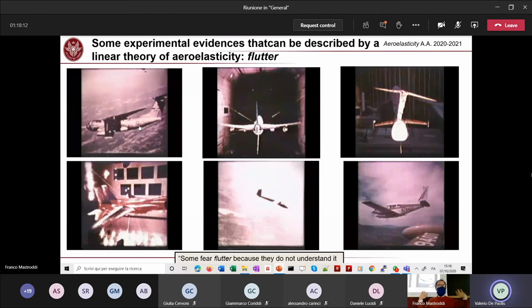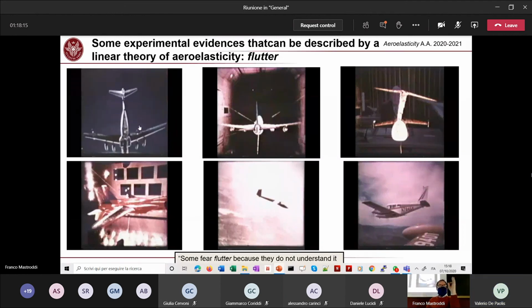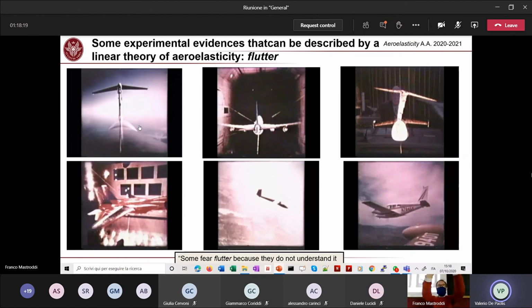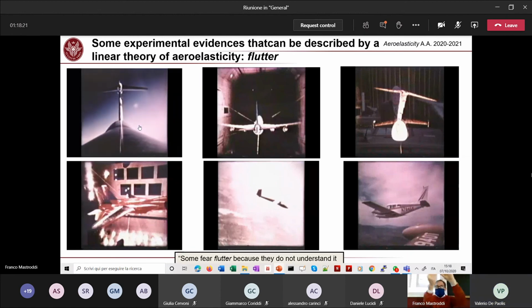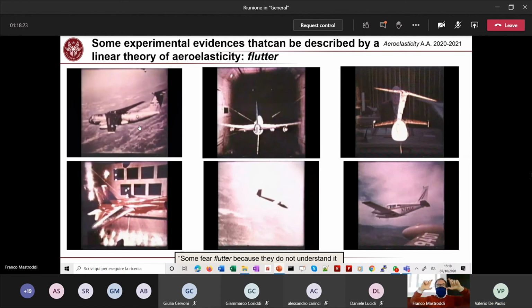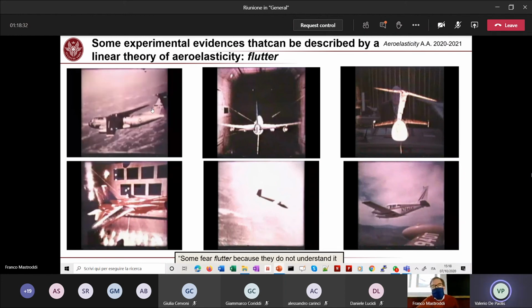So what I'm seeing is a pole exactly on the imaginary axis, before crossing. Just a picture, an exact picture when the pole equals j omega, flutter. I can't believe in that, because in reality, how can I be sure to be exactly on the imaginary axis?